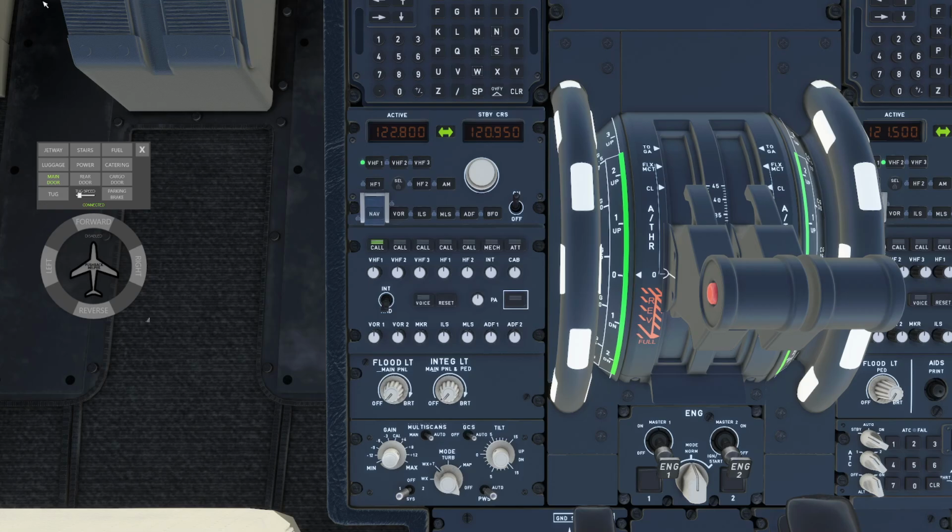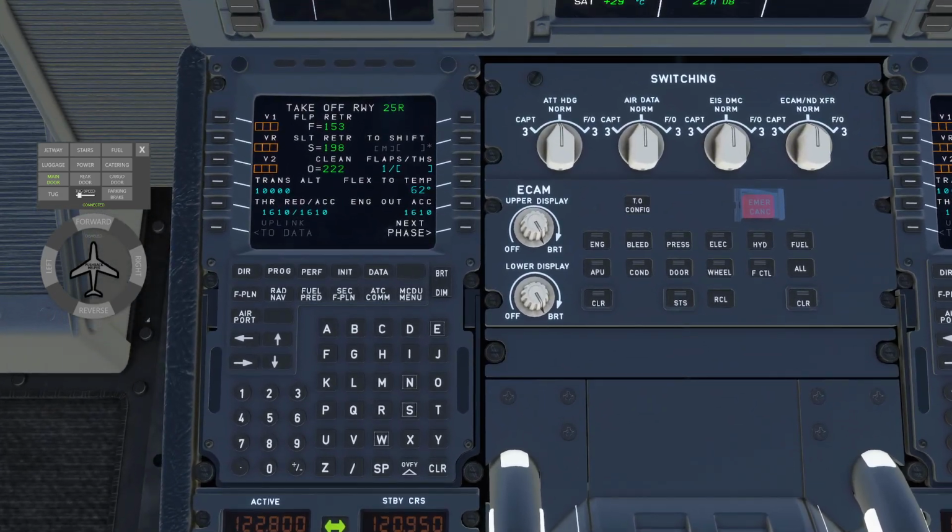So you can see right now we're at 0. Boom, right? Here is the climb. This is climb. You put it there when you want the plane to do autopilot, control everything, the speed and all. Flex is what we'll use to take off, but if you don't set the flex temp, then you'd have to throw the throttle all the way to takeoff, go around, GA. Okay, so there's our little deal. Okay, there we go. All right, so let's go back here, and now 62.